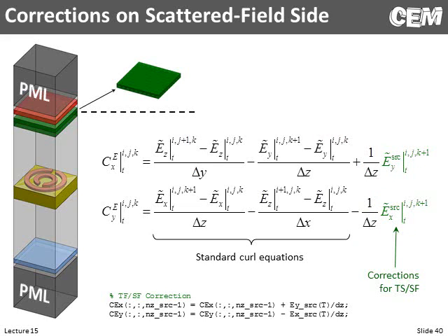So that's pretty neat. Calculate the curl, not thinking anything about a source. Once those are done, then just in those two planes on either side of the total field scattered field interface, we introduce those corrections. And then those same curl terms feed into our update equations, and there's no problem. So we've isolated where the problem we encounter when we're incorporating this. We isolated that work.